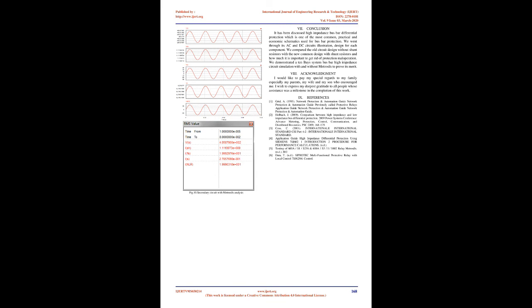6. High impedance differential simulation. Considering a 10 bay GIS double busbar and single breaker 132/13.8 kV substation that includes 4 overhead transmission lines, 3 grid transformers, 2 bus couplers and 1 bus section as per figure 7. Fig. 7. System under fault simulation. As per Table 1, the maximum short circuit current is 40 kA. We will simulate a 3-line to ground fault in busbar 1B using RelaySim Test and PSIM software.